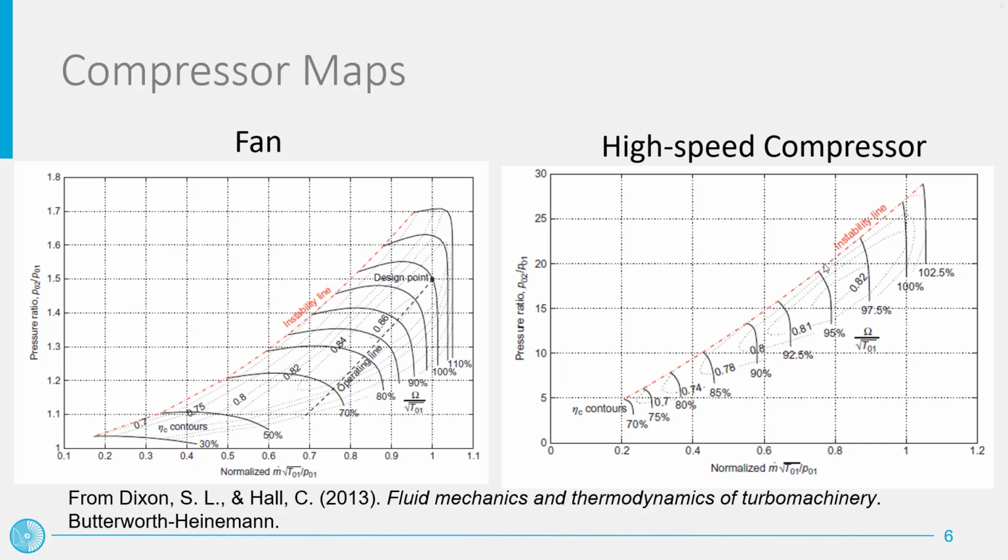Beyond this point, the operation of a compressor becomes unstable. On the right-hand side, the curves end in the choking point, where the flow within the compressor becomes choked, and thus the corrected flow rate cannot further increase. As you can see, the isospeed lines can become very steep in proximity of the so-called choking line, especially in a multi-stage compressor and at high values of the flow coefficient.